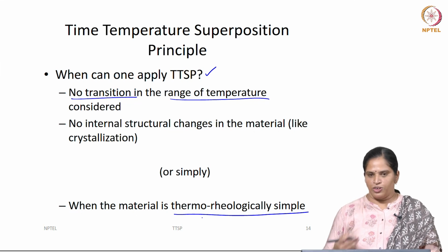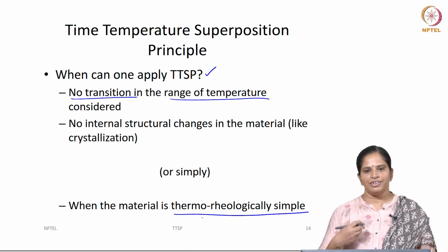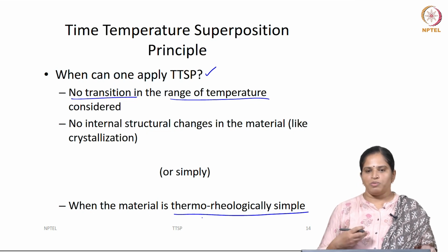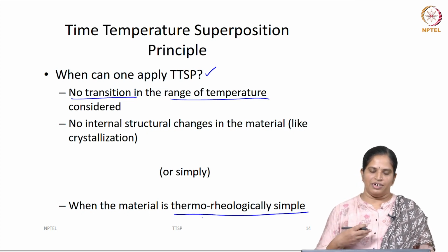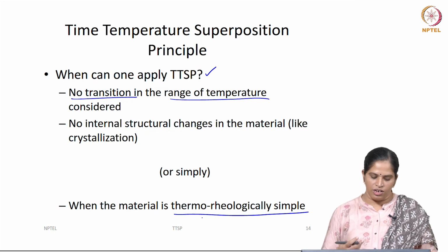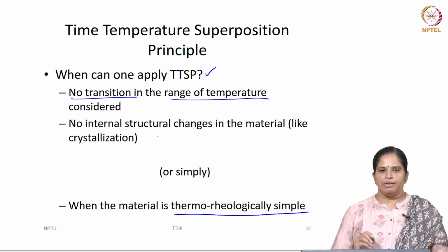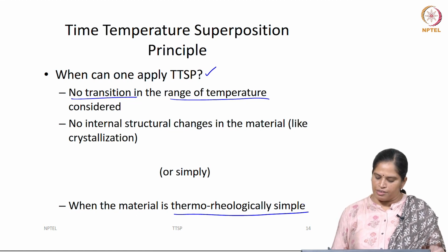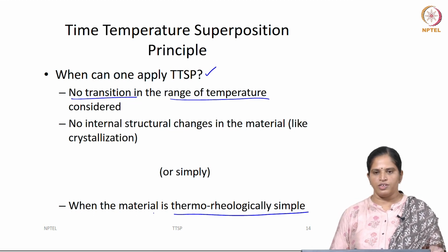Or if you want to describe it in terms of internal structural changes in the material, there should not be any structural changes in the material, like crystallizations etc., happening within the temperature range. If so, then we can call the material thermorheologically simple.